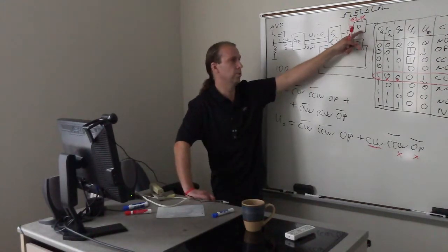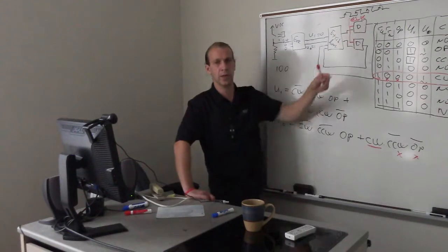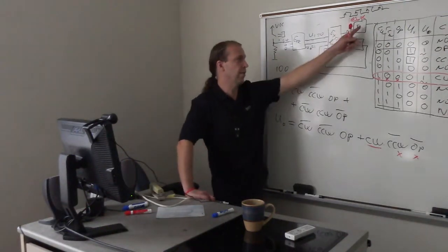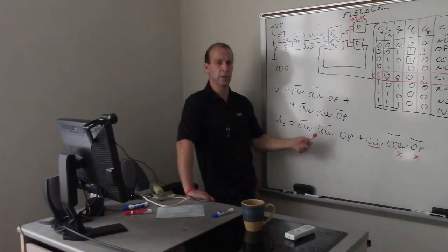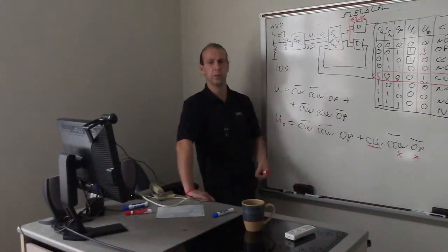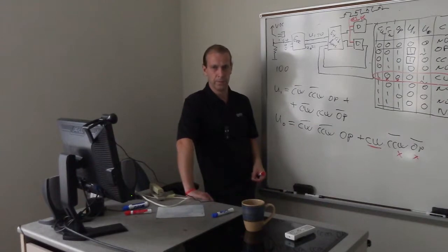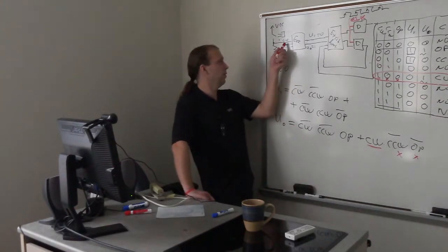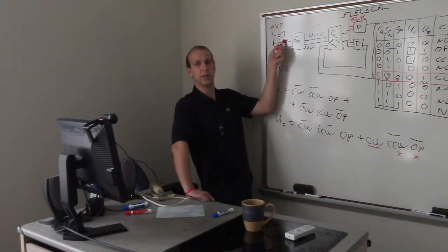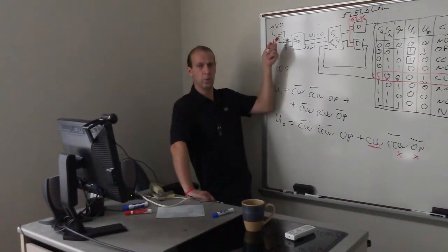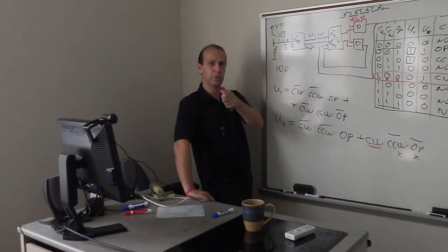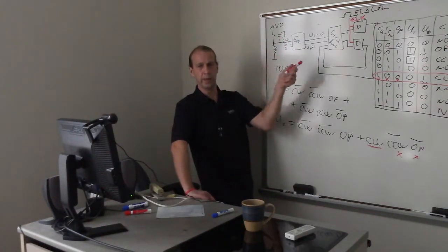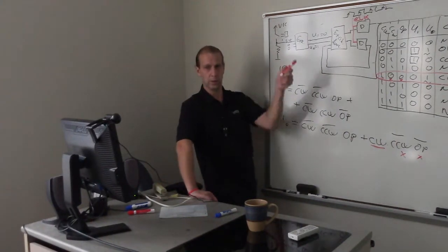So our triggers will move from one state to another: from state A to state B, from B to C, from C to D, and then again from D to A, with respect to the very first diagram. But we still continue giving the CW command. CW command will move from A to B, from B to C, from C to D, from D to A, and again from A to B, from B to C, the clockwise direction.